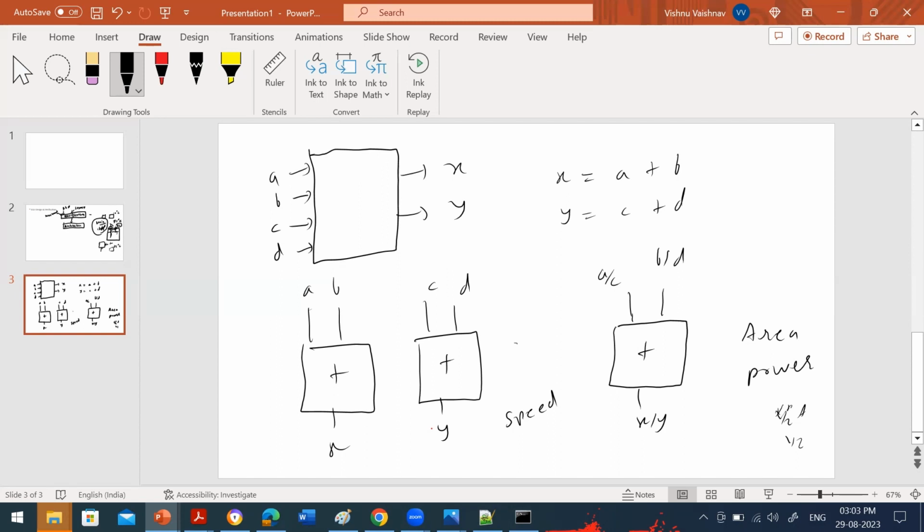And if you put more logical thinking here, generally, if you ask me, I'll say one adder does not take much propagation delay. I think hardly 5 or 7 nanoseconds. If one operation it can perform in 7 nanoseconds, let's say 10 nanoseconds. Let's say the adder takes 10 nanoseconds to do one addition. Still, in 1 second, you can do 10 raised to 8 additions.